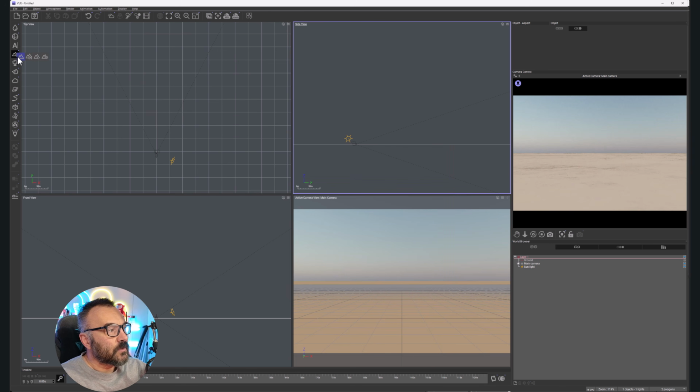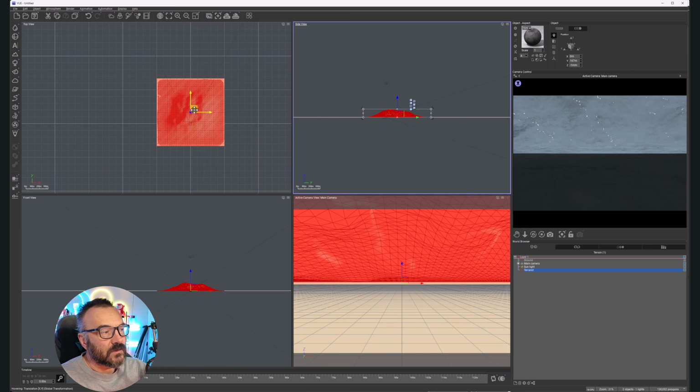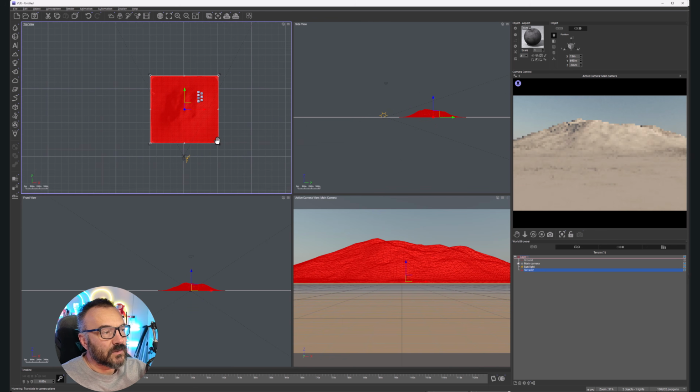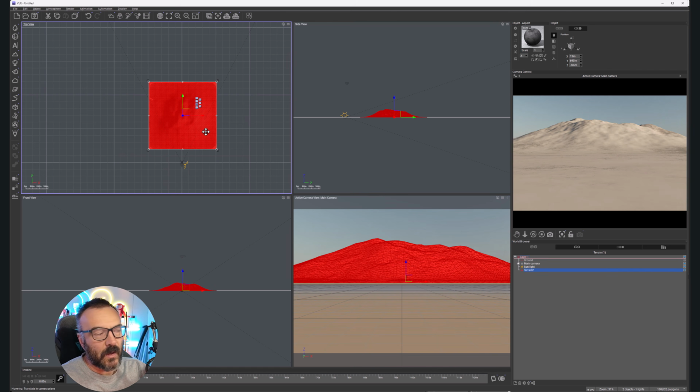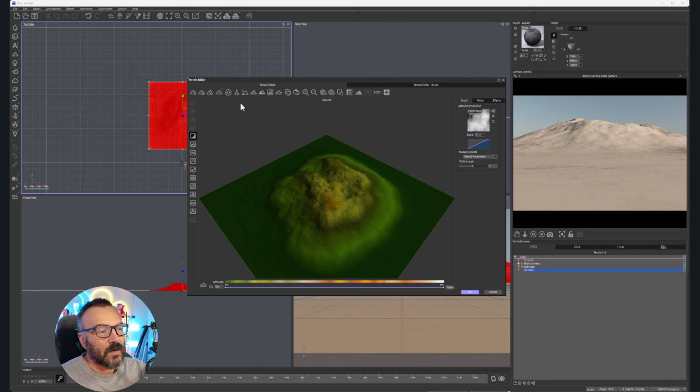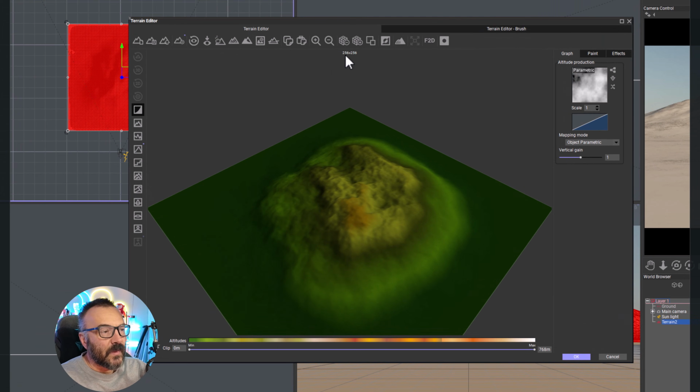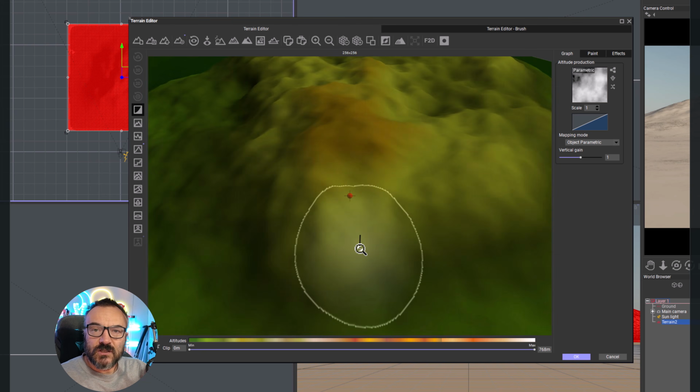For our purpose, we're actually going to use a standard terrain right now, and as I'm creating it, you can see right here we have our mountain created. Let's double click on this terrain to edit it in our editor. As we're creating, you can see it's a 256 by 256 point resolution, so each point represents altitude, height, or loss on our terrain, and a triangle mesh connects between them.